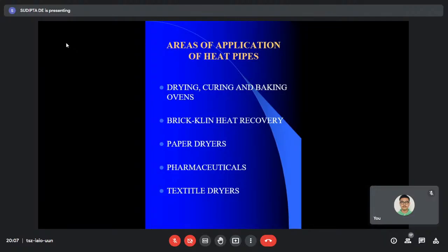That's the standard practice. We call it recuperative heat exchange. In there, the hot gas flows through one channel or tube, and the cold gas flows surrounding that particular tube or channel. Then obviously the conducting material of the tube or channel allows heat transfer without getting these two different fluids mixed.